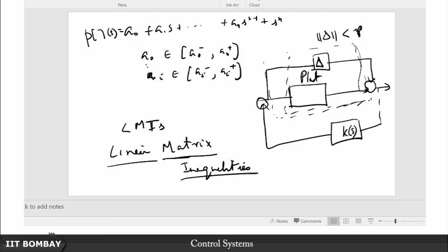For example, an understanding of the Nyquist criteria will help you in seeing how something like a describing function in nonlinear controls works. When you talk about passivity, when you talk about circle criteria, the Lur'e type nonlinearities in nonlinear controls, you will have to harken back to these ideas of Nyquist criteria. Even a classical control technique such as that helps provide you with multiple insights about the problem.